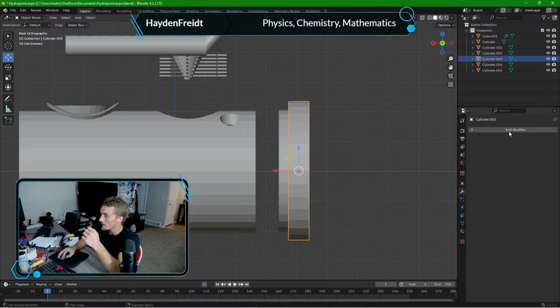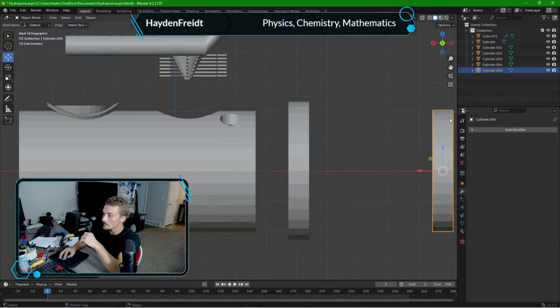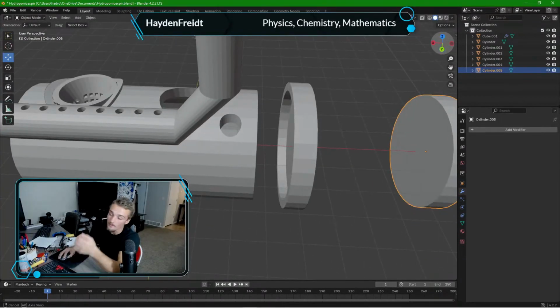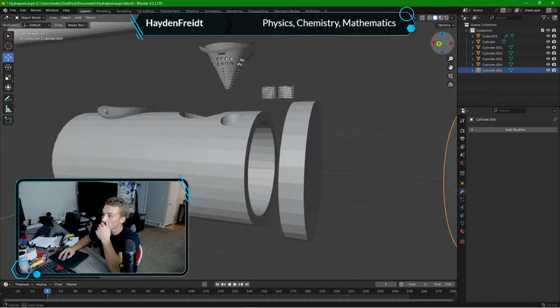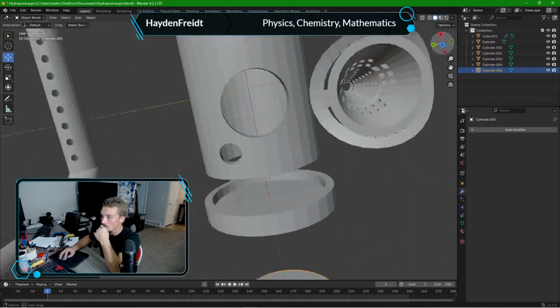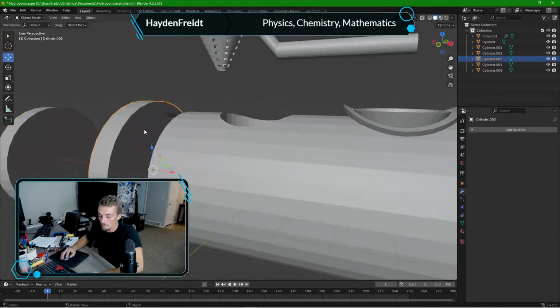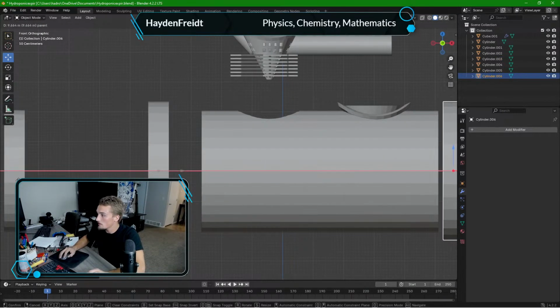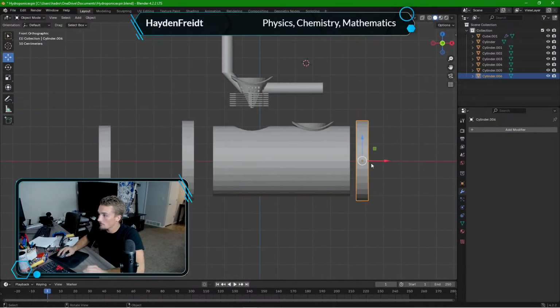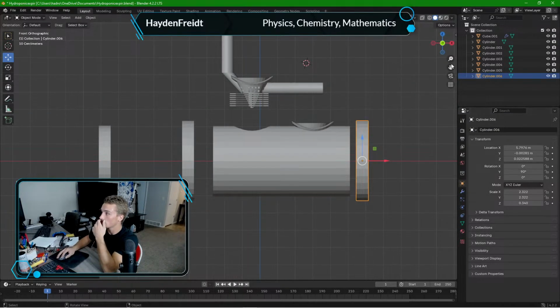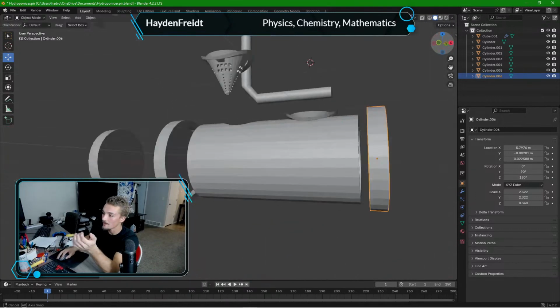So now I'm going to add the modifier again, the Boolean modifier, your best friend. Best friend right there. Apply. I'm gonna move him, make sure it did it. Look at the indent. All right, that's beautiful. And that's our cap. Just like that. I think my spacing is good there. Yeah, it should be all right. And then just duplicate. And take the one over here instead. And flip him around along the z-axis 180 degrees. Now you can't tell, but it did, right? Yeah, it did. It turned around.